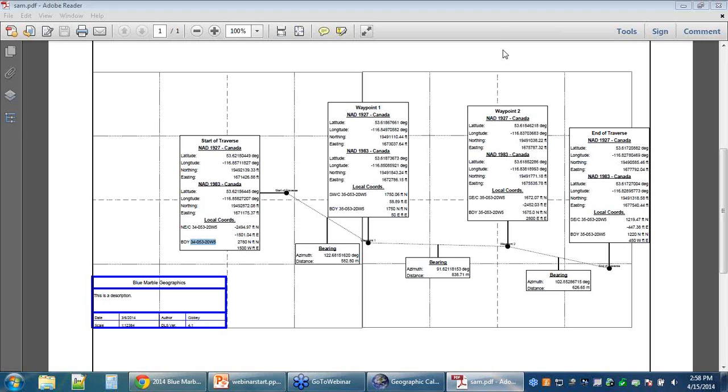I'm just going to make one more pass down the questions and see if I missed any. Looks like an earlier question. I'll just point this out for everybody. The ATS files, there are various measurements in feet, meters, all the various versions. The question is, are they all supported? And yes, if you take a look down under that string category, you'll actually see subfolders for the boundary versus corner types. Under each of those, you'll see each of the grid versions, and then you'll also see variations.